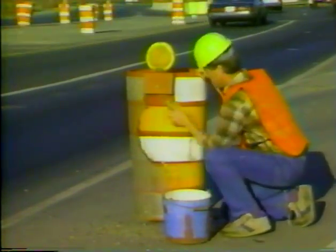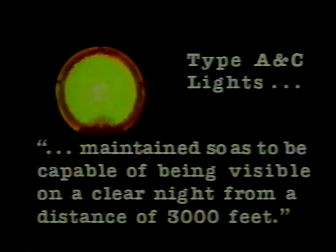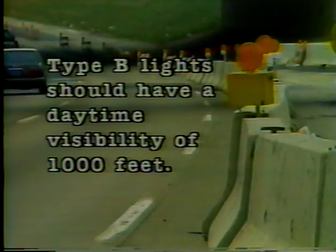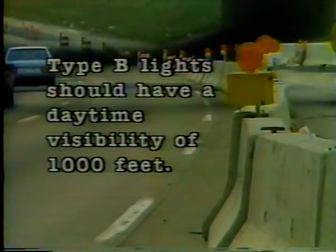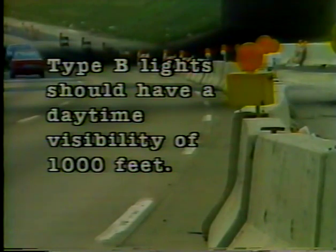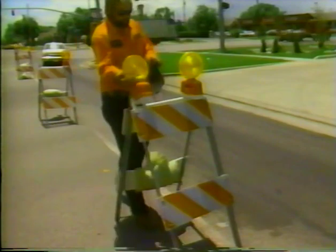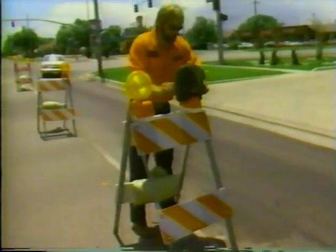Lighting devices must be maintained too. The manual has established minimum performance standards for warning lights. Type A low-intensity flashing lights and Type C steady burning lights should be maintained as to be capable of being visible from a distance of 3,000 feet on a clear night, providing there are no sight obstructions. Type B high-intensity flashing lights should have a daytime visibility of 1,000 feet without the sun directly on or behind the light. As with other devices, warning lights must be maintained at an acceptable level of safety.